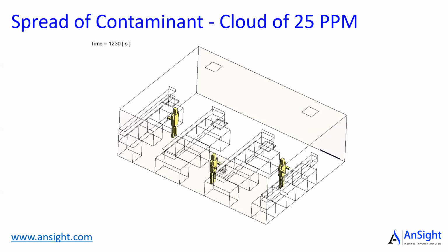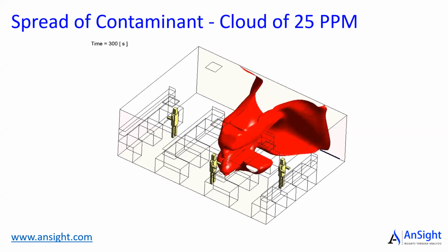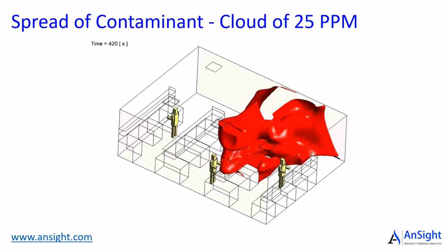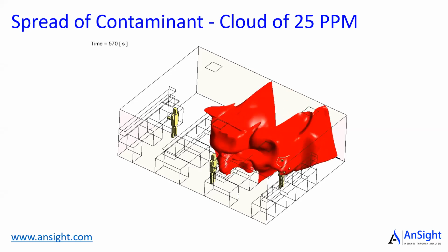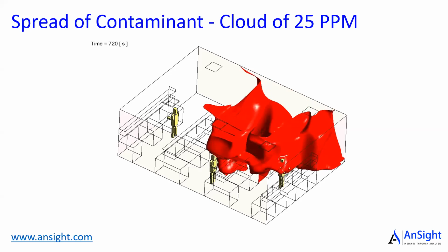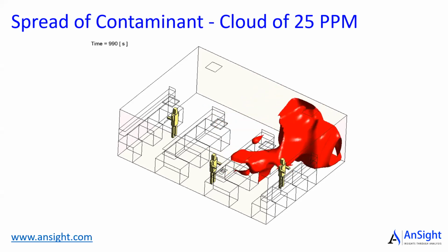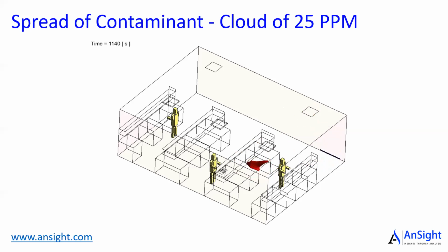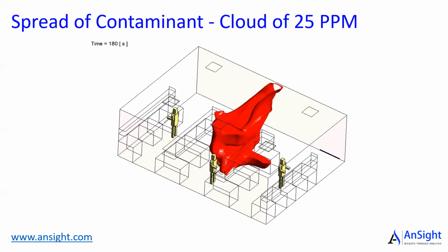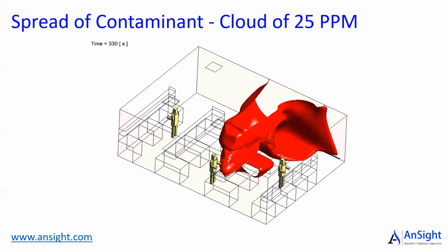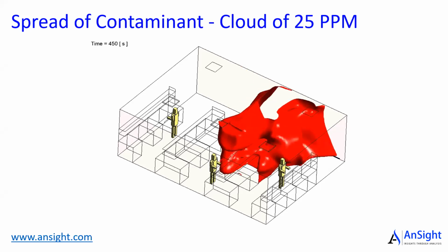And you can see when this cloud gets trapped between the cabinets, if you have a stagnant zone, whether it's under the table, between the two cabinets, or sometimes between the two beams near the ceiling, when the contaminants get trapped in such spaces, they are the last ones to leave the space. Air cannot find them. They're hiding behind those cabinets. And so air has to do extra work to push them out of that space. Okay.